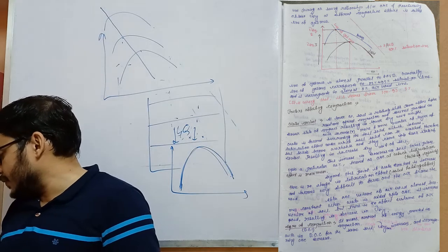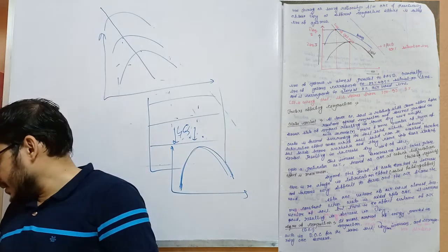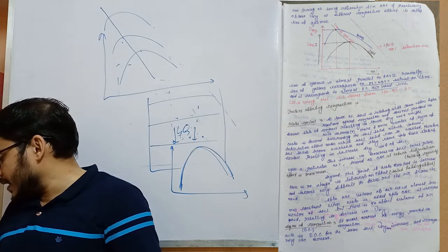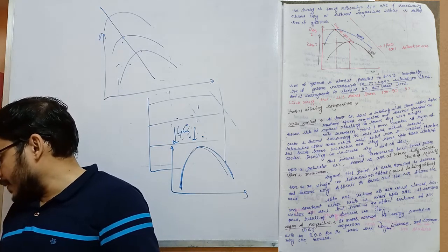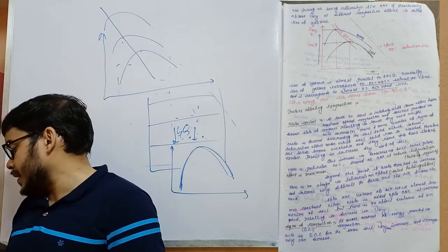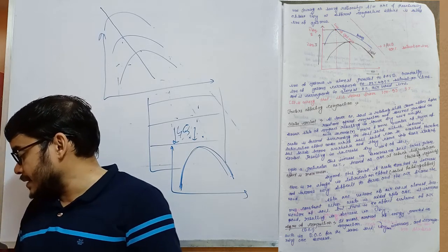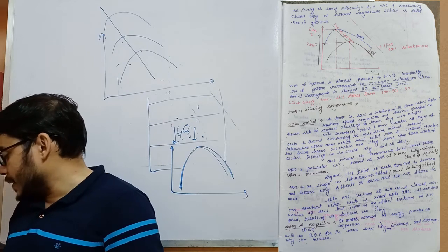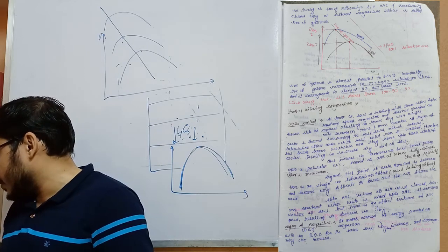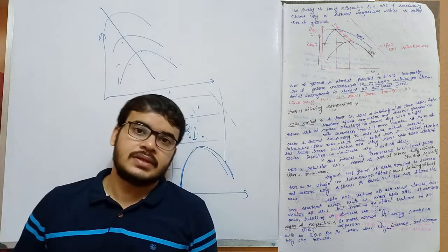Beyond this point, if water content is increased, there is no change in lubrication effect and it becomes very difficult to force the air out of the voids. After OMC, the volume of air voids almost becomes constant. When water is added beyond OMC, it increases the volume of the soil, but there is no effect on the volume of the air voids, resulting in decrease in gamma dry.